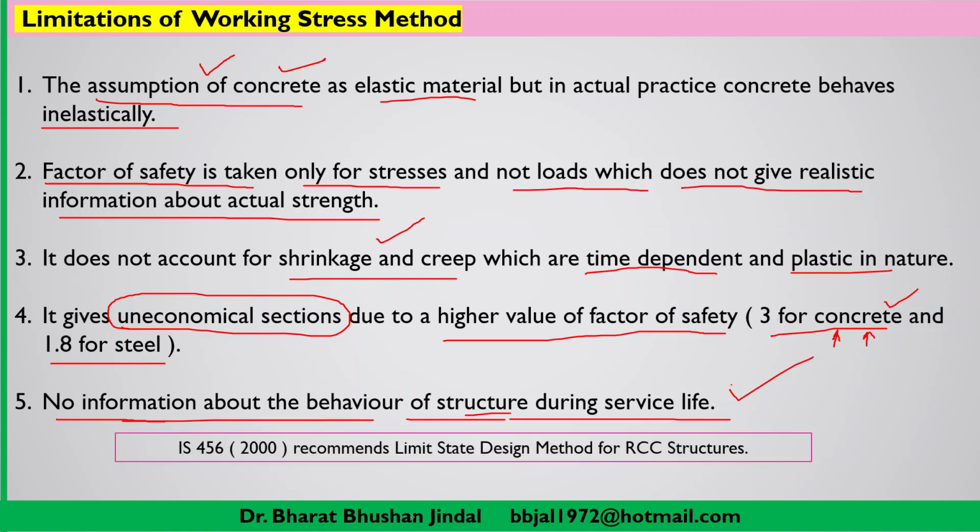So IS 456 now recommends the limit state design method for RCC structures. You may use the working stress method in the design, but then you have to face all these limitations, and you have to compromise on some of the properties of the structure as well as the economy.